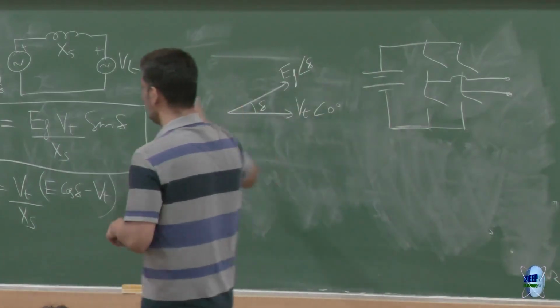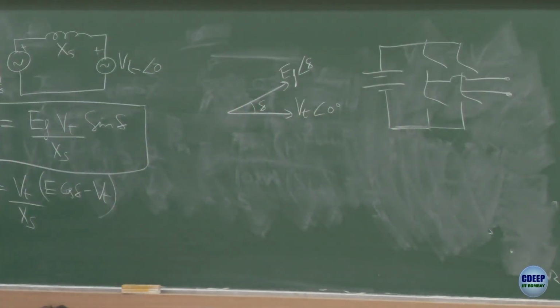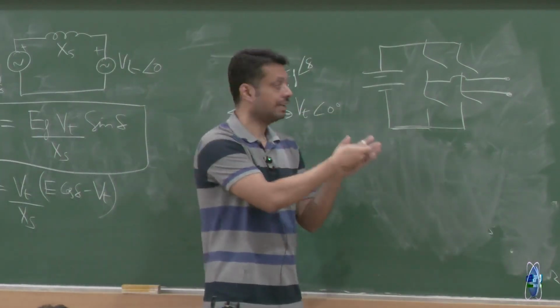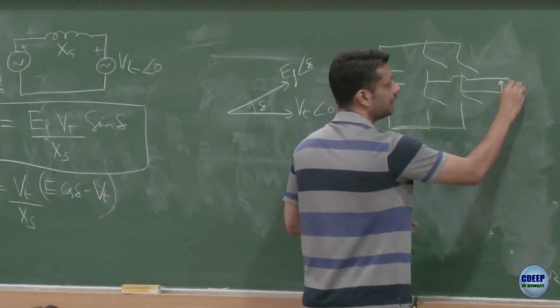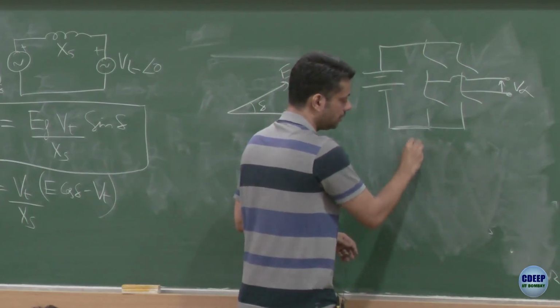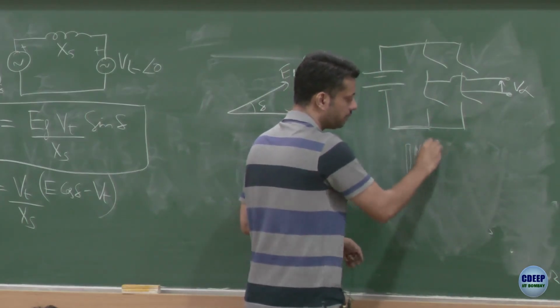Left side is this, right side is of course the infinite bus or the grid. You remember that circuit, right? That was the H-bridge inverter which we have studied a few lectures before. You remember we can do sine triangle modulation of this and we can generate a voltage here, let me call it V alpha, which looks like these PWMs and so on.